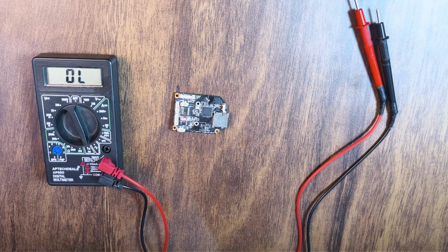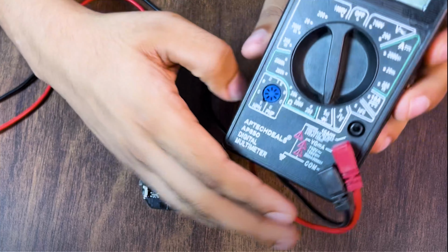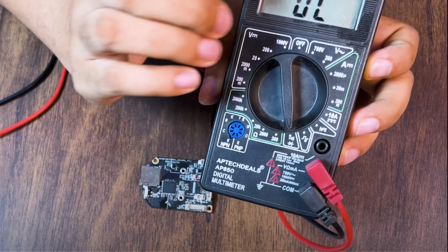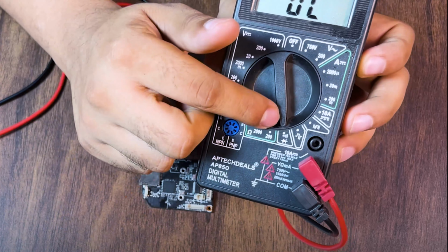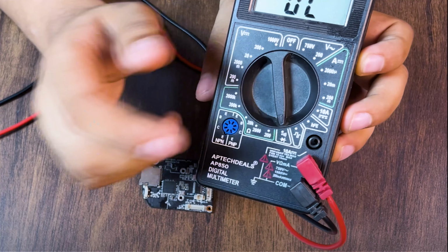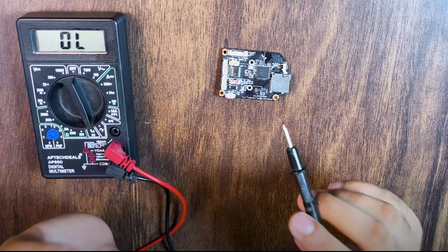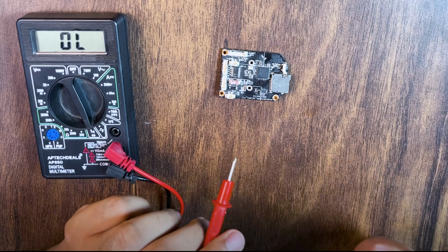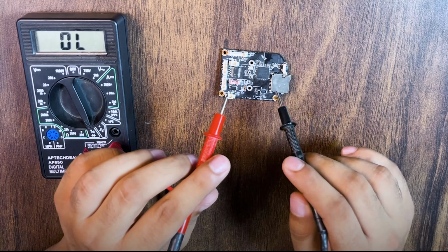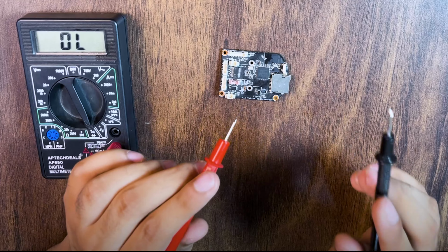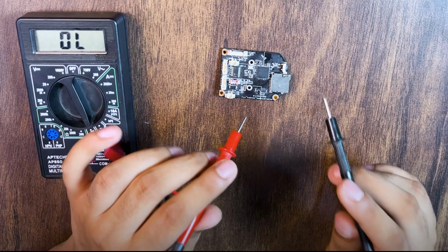Well, now, first what we'll do is test the ground port. The ground port is labeled on the motherboard, and for that, we'll use our multimeter in the continuity mode. In my multimeter, the continuity mode is shown by this symbol of Wi-Fi, which is for the beep or the diode symbol. And what I'll just do is take these two probes. I'll put one probe on the ground port and another probe on any other metallic area which can be considered as ground, or which is actually the ground of that motherboard.